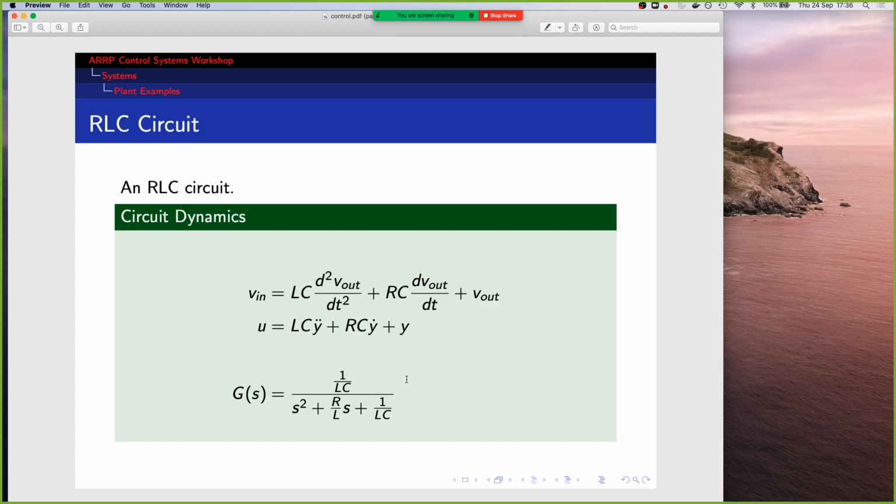And then obviously I've derived the transfer function here. Just be aware with transfer functions, we usually like to have the leading term of the highest order s in the denominator as 1. So we just factor things out so it looks like this, and that's generally a standard form for transfer functions. That's why you've got these sort of weird looking fractions that may not make sense at first glance, but it's because we want this leading term coefficient to be 1. Excellent. And this one's obviously a linear equation as well.